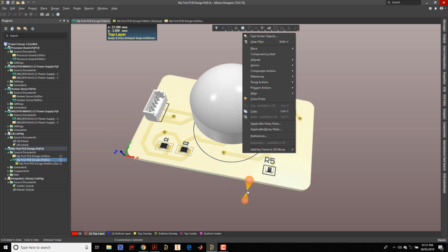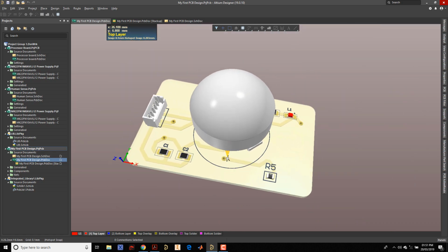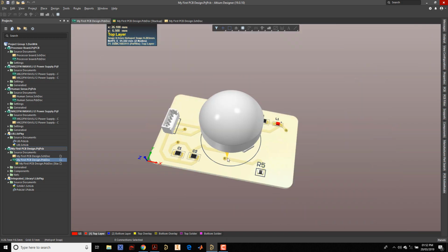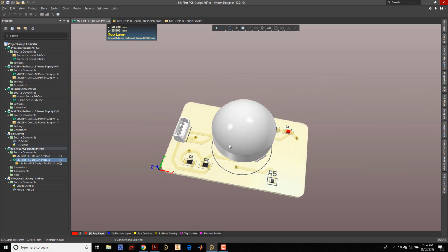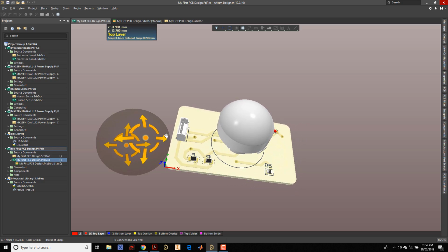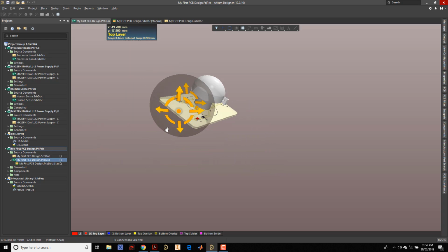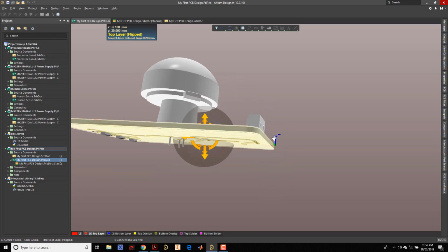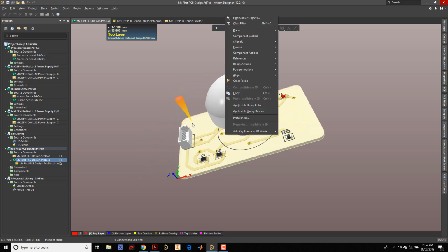All right. Now to rotate it, I've not been showing you how to rotate it. To zoom in, you press the middle mouse button. That's zooming, and then you move. To pan, press the right mouse button. To rotate it, press Shift and then press the right mouse button. So Shift plus right mouse button rotates it. Middle mouse button zooms. Right mouse button alone pans.